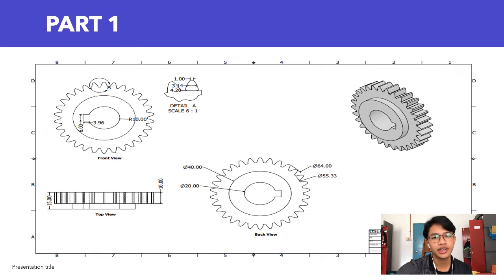Then create a rectangle with a dimension of 7 by 6mm and cut it through all.